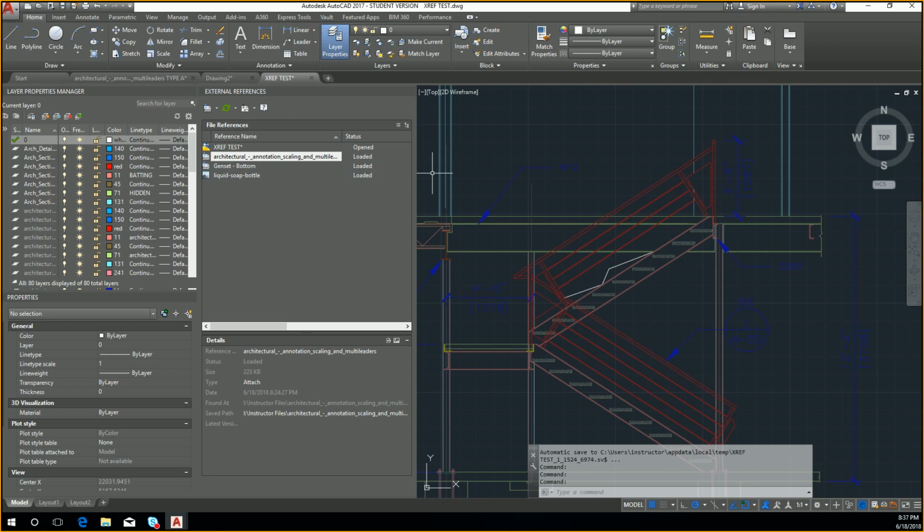So there's differences in what those mean. Unload is good if you want to do your plot after you've done your references. So you drew an addition to your door, like a bookshelf at the height of your door, and you just want to reference it. Then you would unload it, plot your bookcase, and you're happy. If you're completely done with it, you will never need to reference it again, or for the foreseeable time, you can fully detach it and break that reference away.